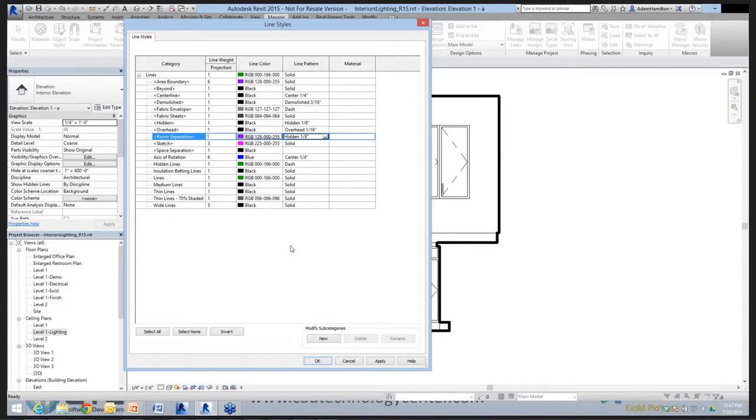So utilizing the ability to create additional lines, additional line weights. It's important to know that line weights go up to a 16, but that is entirely too big. So it would be good to create more steps up. And the ability to create different shades. So having the grayscale option as well as the black option allows us to have different depth of line weights behind it, and the patterning that we can use. And sometimes it's important to know this patterning because of the size.